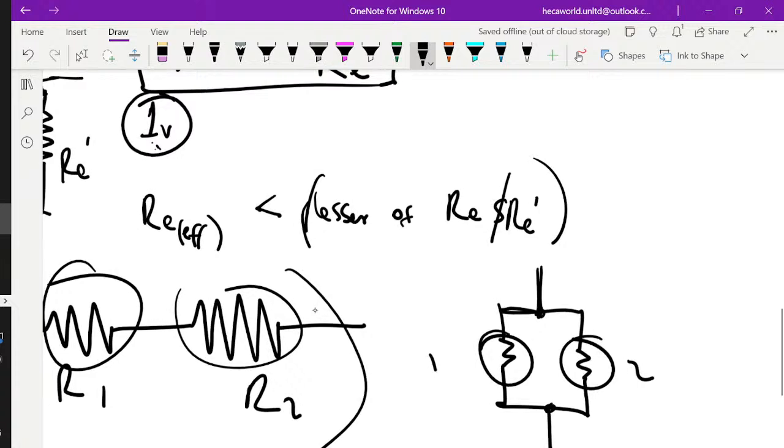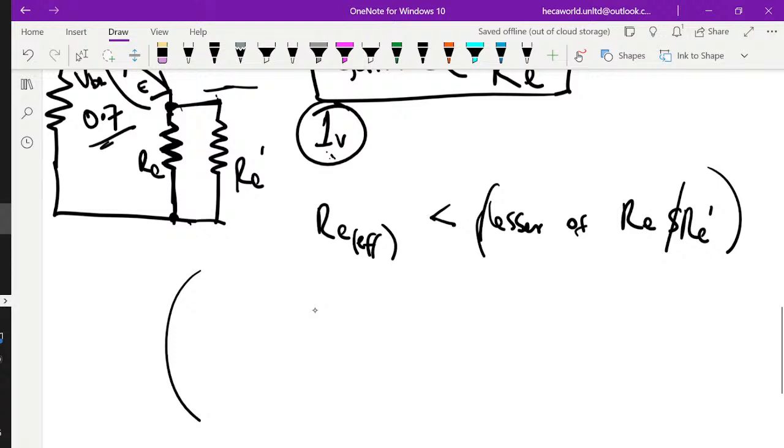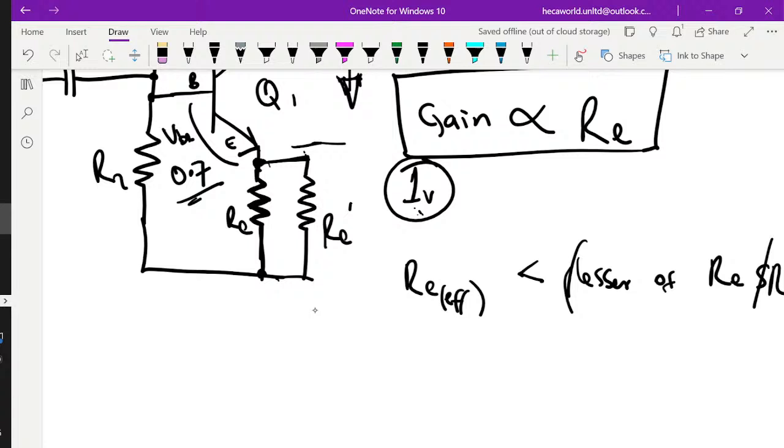All right, so let's just delete this. You can watch our video on resistor analysis and stuff like that. I think it's in our basic electronics. Now, all I wanted to show you here is that instead of connecting a resistor in parallel, I can connect a resistor in series with a capacitor. And this resistor is only called into action when it is operational, not during biasing conditions, because the capacitor will block DC conditions, so it will take this out of the equation.